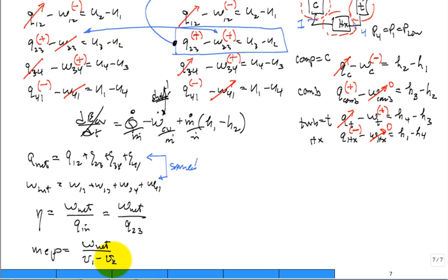How many people have an engine in their car and know, oh, it's a 2.2 liter or a 5 liter or 350 cubic inch, or whatever size the engine is? What are you quoting there? It's the displacement volume, isn't it? Isn't that the displacement volume? So if, let's say it's an 8 liter, just to make the math easy, and I have 8 cylinders, that means each cylinder has 1 liter's displacement volume.